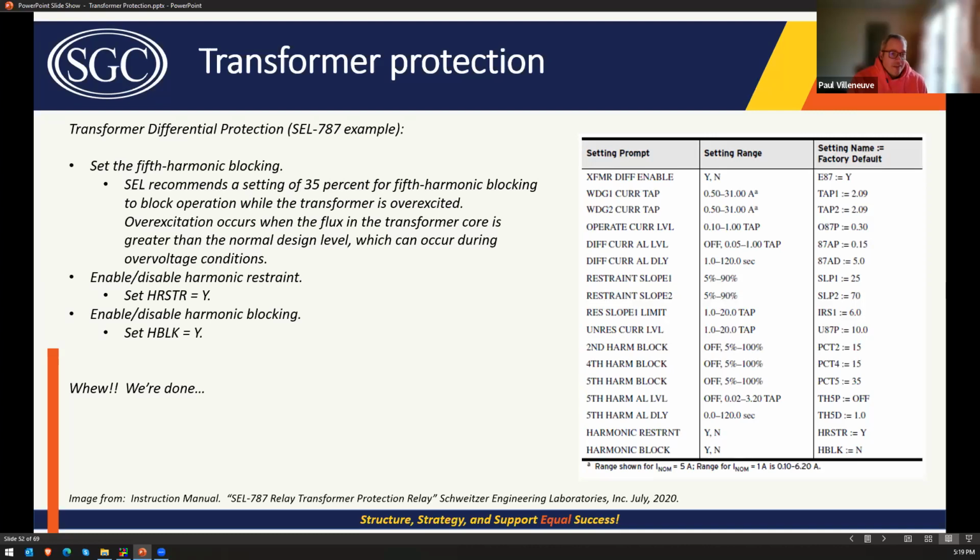I think it's usually more a problem with the frequency than the voltage, because most of the time these transformers are maybe 106 per unit or something like that. But I've never seen a volts per hertz trip except when it was connected to a generator that was trying to start up, and it tripped because the generator was still at 50 hertz. There was no generator circuit breaker. It was just rolling up slowly, and they were trying to push it too fast. That was the problem. That's the only time I can think of.